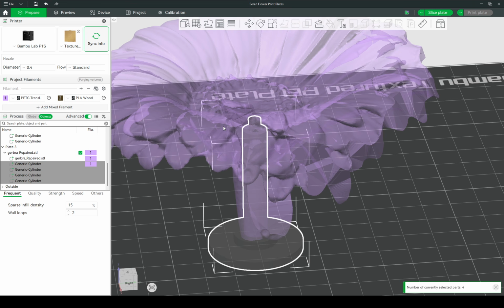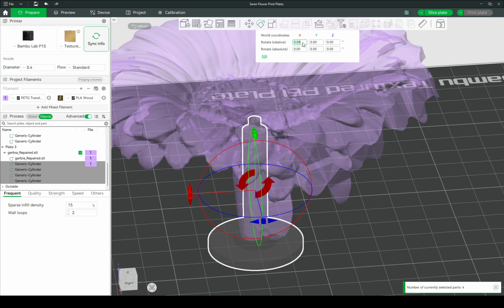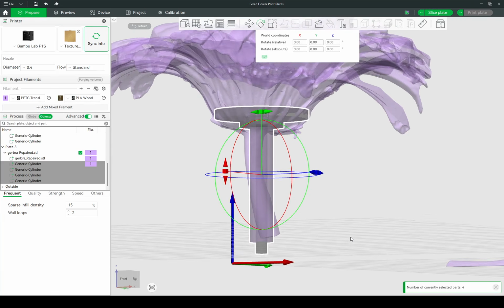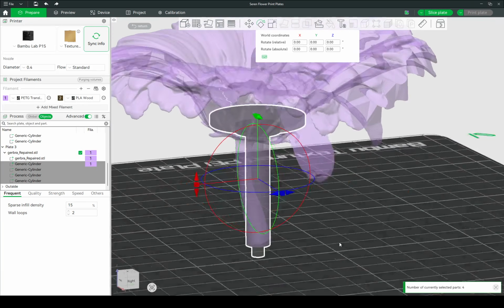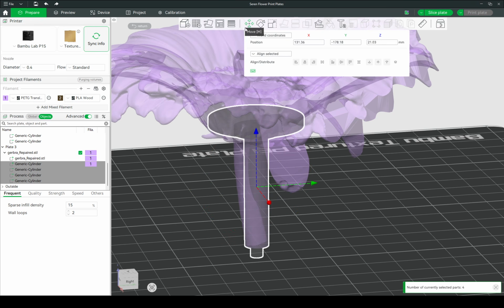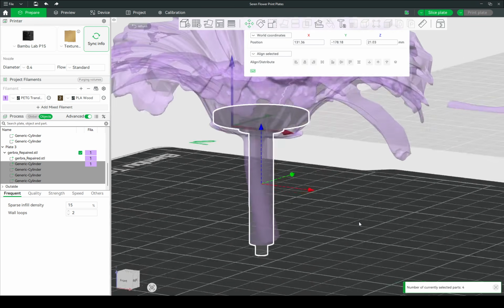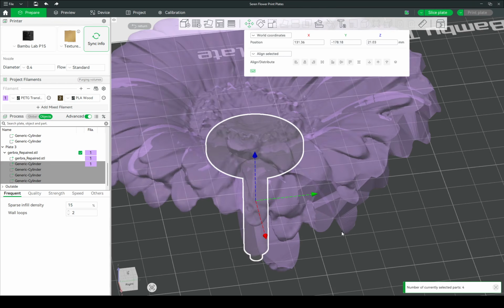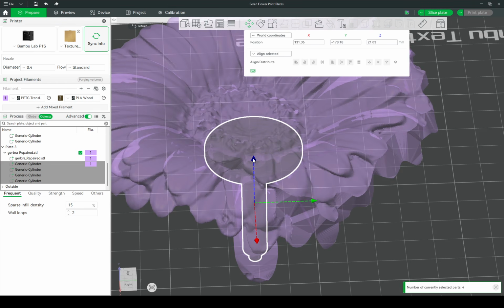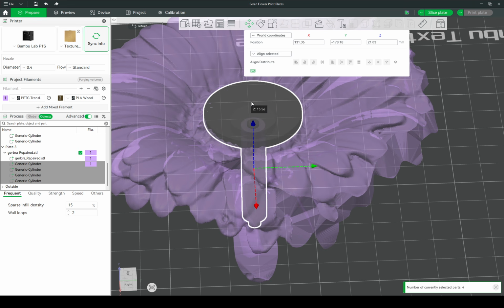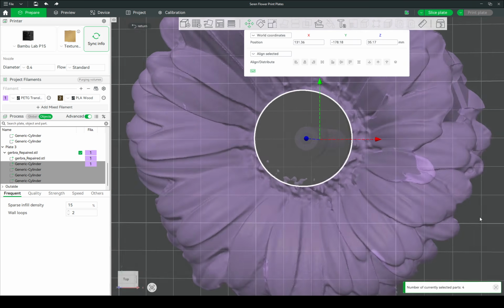And now we've got to move this whole thing into position. So it's going to flip 180 degrees and sit underneath this main part of the pedal here. So we'll do that on the x-axis, flip it to 180. Okay, and then we get to move this around just using these basic direction arrows. So I'll move it up. And what I want to look for is kind of, I'll look at the top and try and center it.